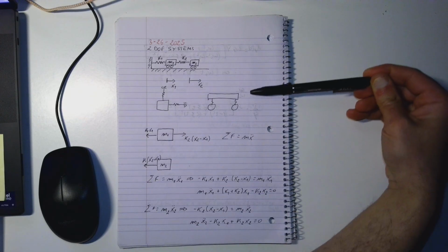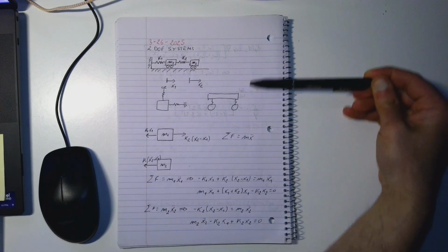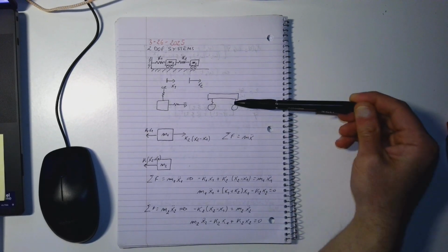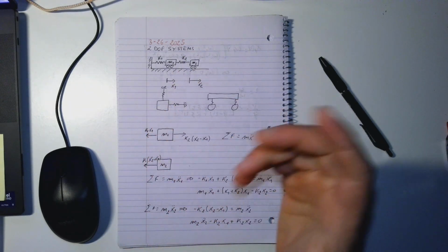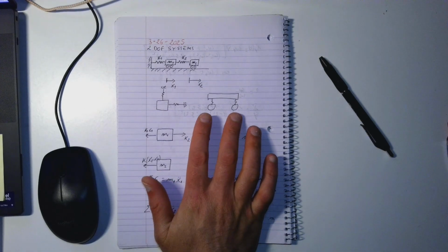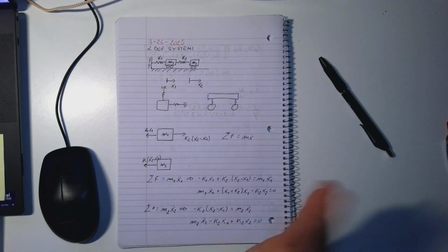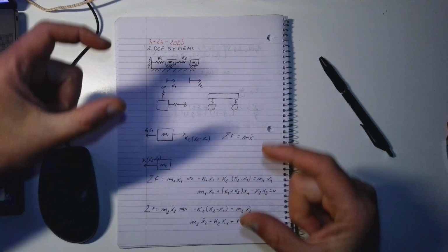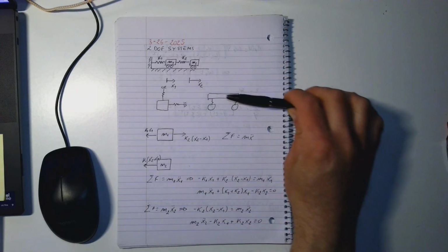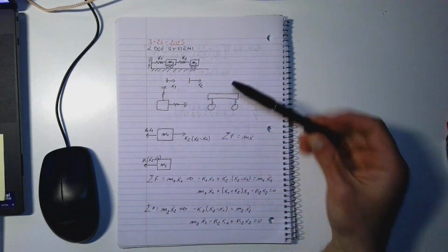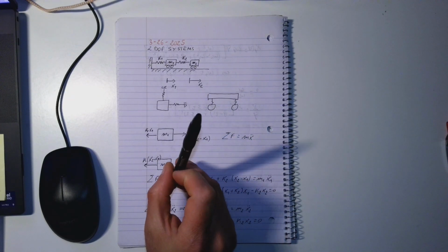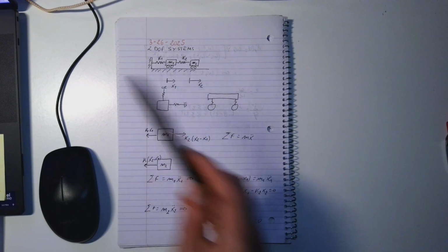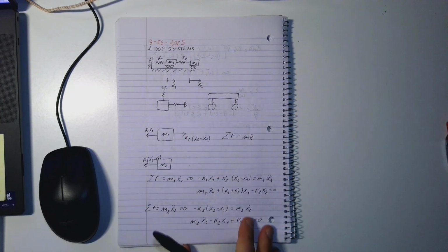In this case the car can move in the vertical direction because the two springs can be contracted or stretched by the same amount. But if the two springs are contracted or stretched by a different amount, it means that we have also a rotational degree of freedom. So again, the number of masses is a good indicator, but it's not enough to determine how many degrees of freedom we have.